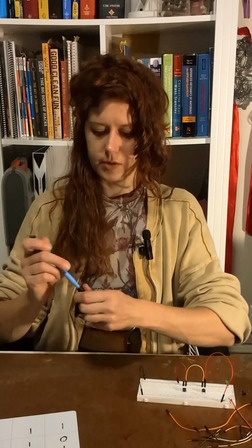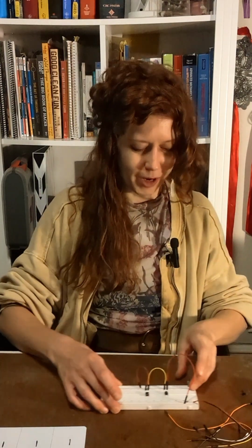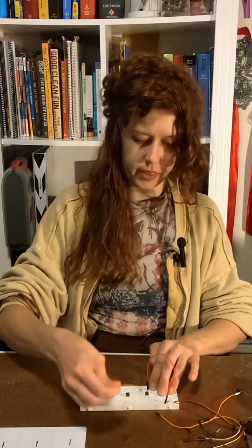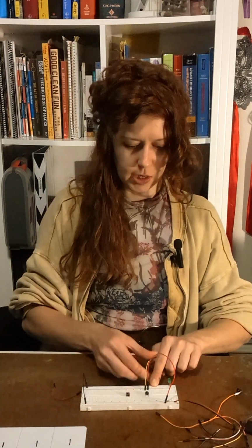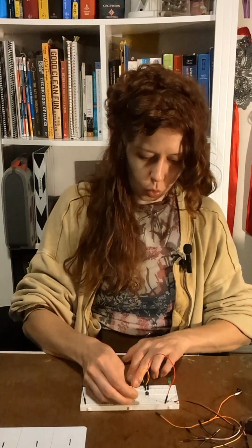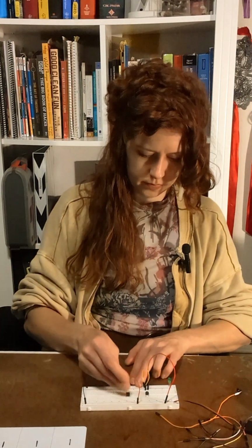Okay, so now that you've had some time to think about how to build it, and if you haven't, go ahead and pause the video and come back to it when you want to check your answer. Okay, so we are going to stick with our 2 push buttons. You got to connect to the negative side of the circuit. And in this case, we have 2 parallel loops. So there are 2 paths for the electricity to flow, either through button A or through button B.